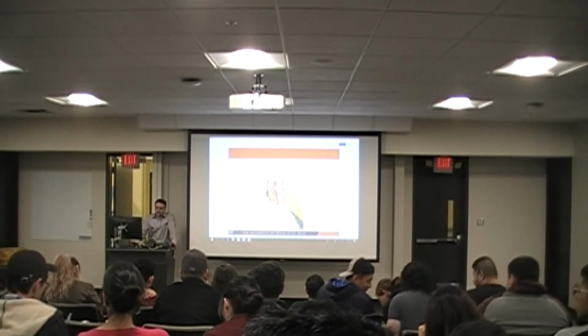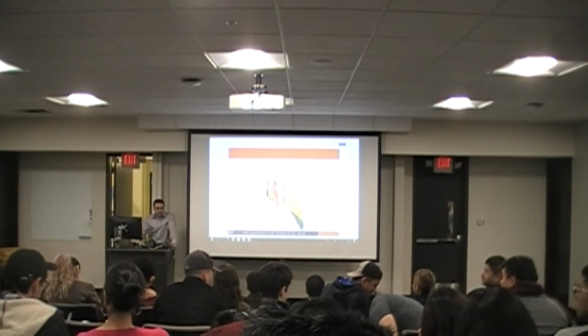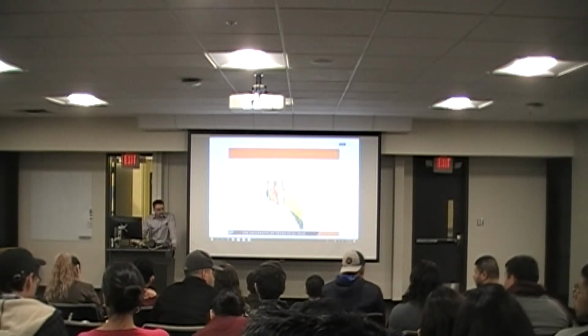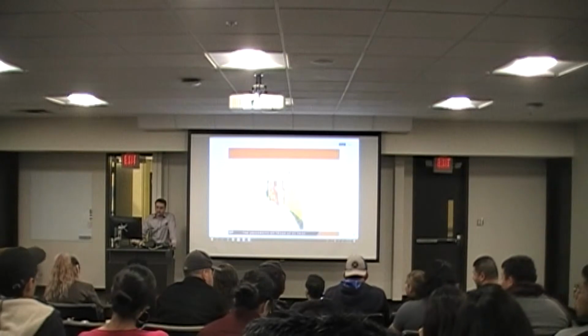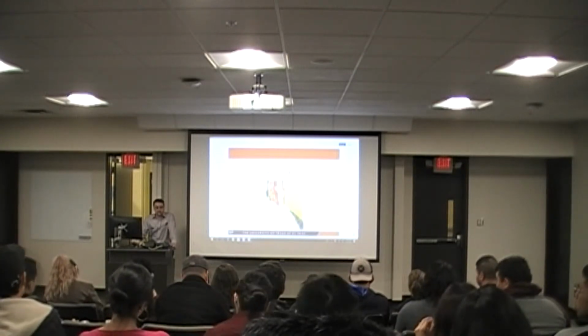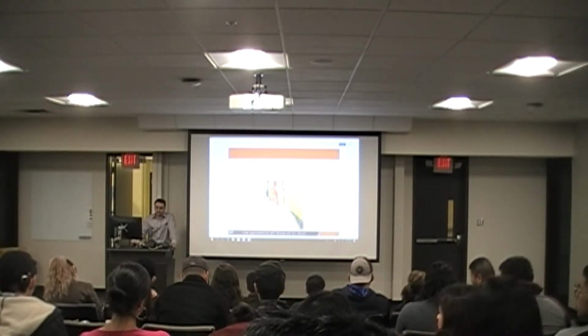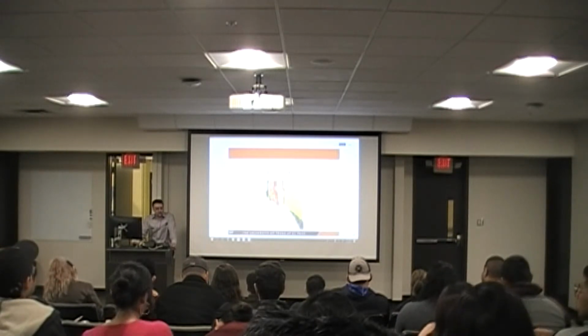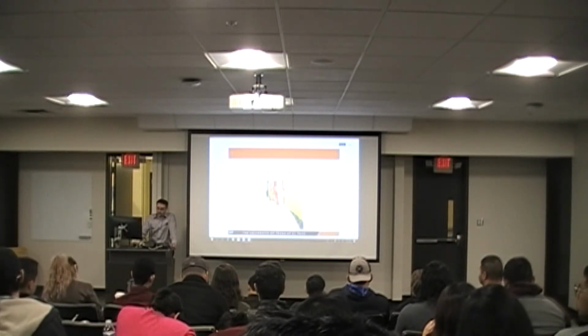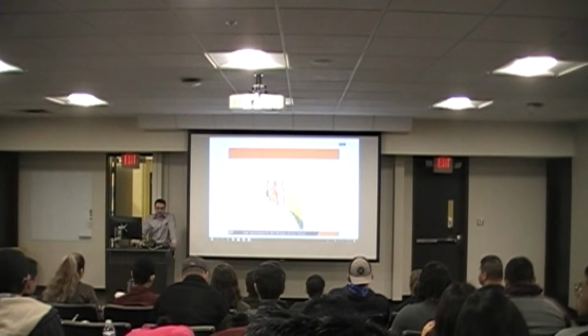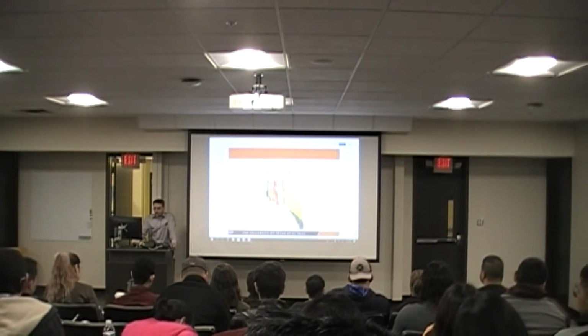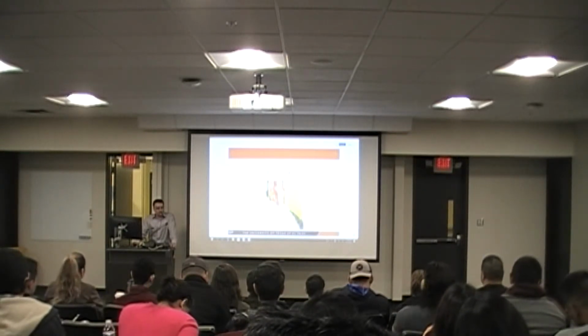So for us, in geotechnical engineering and civil engineering, for anything related to construction work, we use these 2, probably 95% of the time with the USCS designation. Unless you're specifically in pavement work and runway work, most of the time use the AASHTO designations. But other than that, these 2 are going to be the most important ones.